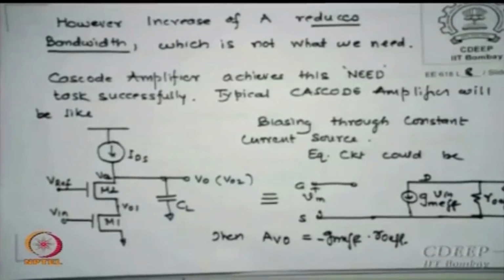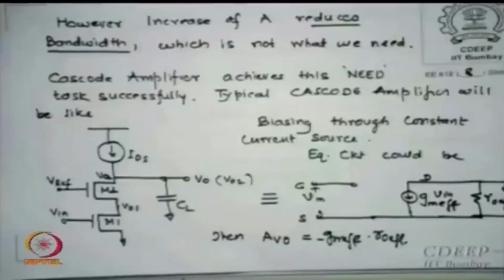common gate, and the advantage, when I now show you common gate, will be very obvious. Like in the case of common base amplifiers, the current gain is unity, same is in this case. The common gate amplifiers do not give you any current gain, because source current and drain current are the same, so it is almost unity current gain. But what is the advantage?